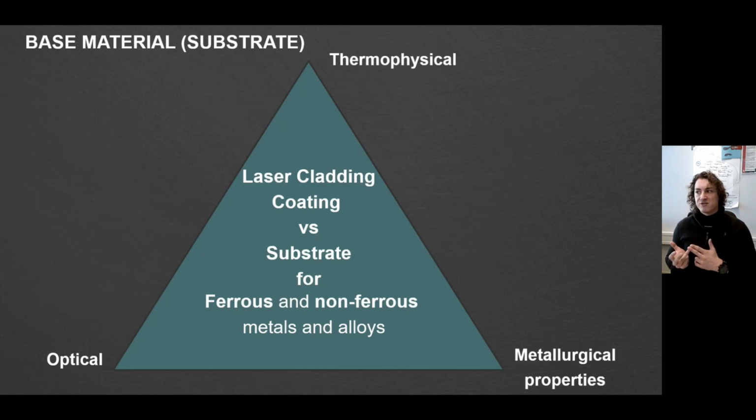They might have different thermophysical properties, thermal conductivity, and of course they do have different metallurgical properties, which is based on their chemistry. In my opinion, to have a successfully working process, there are a couple of tips which I can give you. What you have to look on to combine your base material, understanding base material together with your hard-facing or laser cladding process.